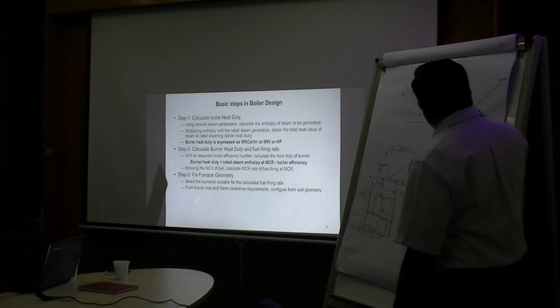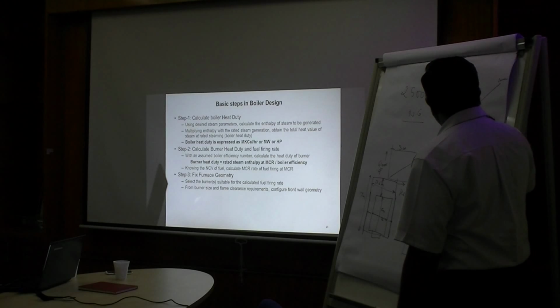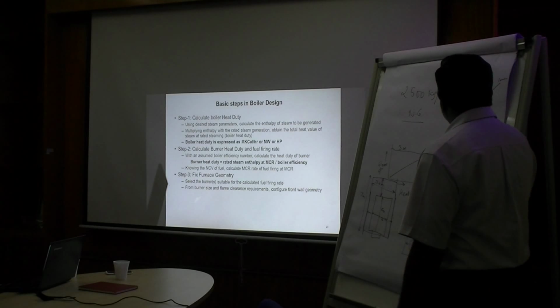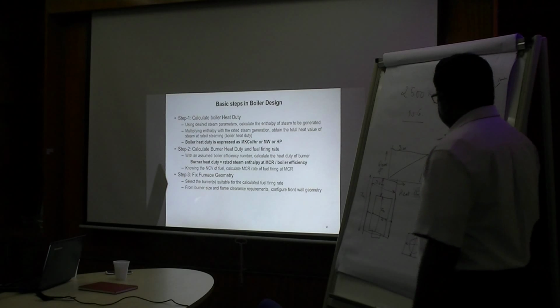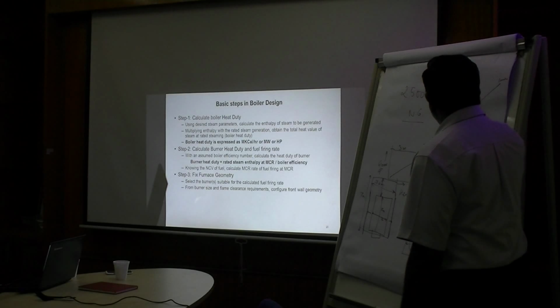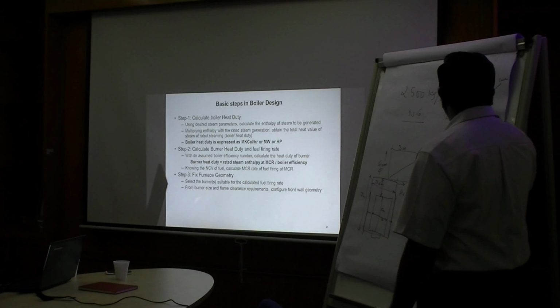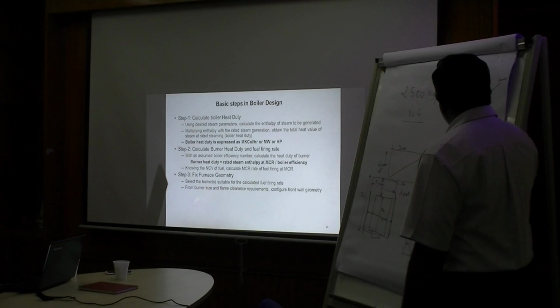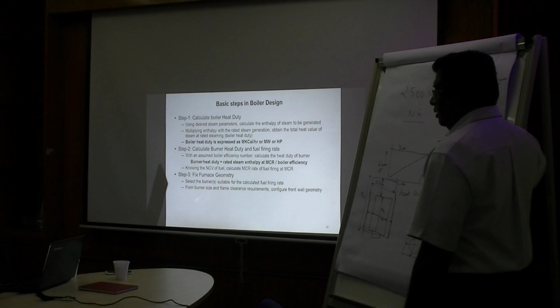But as soon as you increase from here to here, this burner cannot perform anymore and you enter the zone of 2 burners. The number of burners will change to 2. Then you go from here up to, let's say, 120 tons capacity, and you switch over from the zone of 2 burners to a zone of 3 burners.